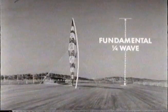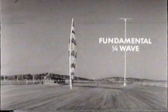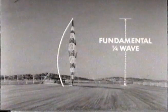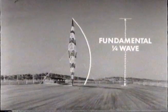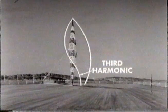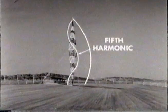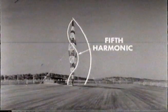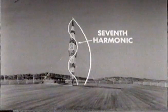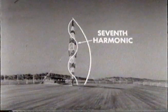A grounded or Marconi antenna is the fundamental quarter wave antenna. It will resonate at any odd harmonic of the fundamental, at the third harmonic, for example. At another time, it may be made to resonate at the fifth harmonic, the seventh harmonic, or any other odd harmonic of the fundamental quarter wave.